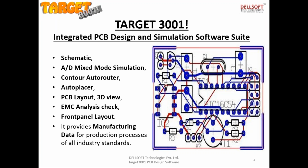So when we design our circuit by putting these components and creating the circuit, that is like sketching only. So if you want to create those circuits into the PCB, you have to be more optimized. So that optimization work will be performed through this auto placer and auto router. Okay. So when we created the layout, you can see the 3D view. You have the EMC analysis check, front panel layout, and it creates the manufacturing data also.